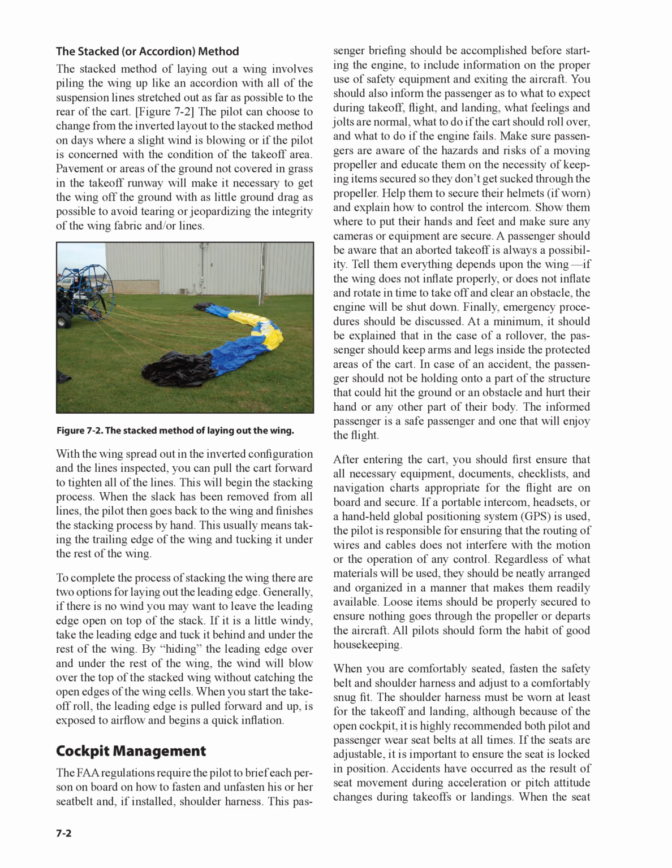A passenger should be aware that an aborted takeoff is always a possibility. Tell them everything depends upon the wing. If the wing does not inflate properly, or does not inflate and rotate in time to take off and clear an obstacle, the engine will be shut down. Finally, emergency procedures should be discussed.